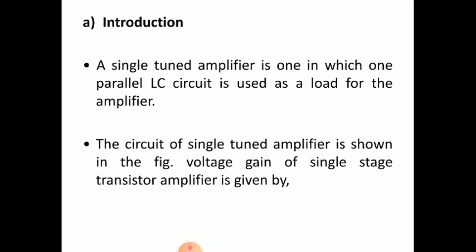Now see the introduction about the single tuned amplifier. A single tuned amplifier is one in which an inductor in parallel with a capacitor, that is a tuned circuit, also called a tank circuit, is used as a load for the amplifier. You can remember the basic amplifier circuit. If you remove the load resistor and replace it with a tuned circuit, that is an inductor in parallel with a capacitor, it will become a single tuned amplifier circuit.